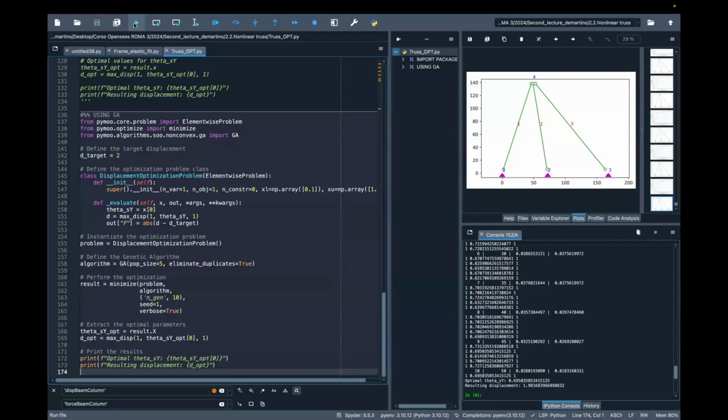What I want to say is, if you have a numerical model and you apply this approach, and you find an elastic modulus of steel of 100 gigapascal, this makes no physical sense. So always keep in mind that the model should work on a physical basis. Otherwise, you move to fully data-driven. But I don't know if you need finite element analysis. You can move to machine learning, skip the finite element part, directly move to fully data-driven, and you skip the model. So this is a very powerful technique. You can always tune your model, but think about whether the input parameters make sense.